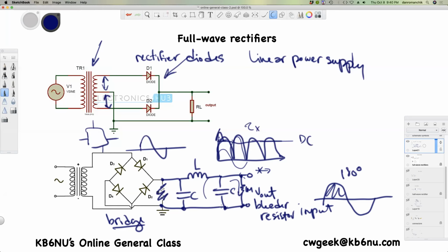So that bleeder resistor will discharge that current right away, and the voltage will drop to zero. I even go a step further. Anytime I do something like that, I'll wait a minute or two, then put my multimeter on it just to check and make sure that there's no voltage left across the output terminals. And if you're doing that, make sure you unplug it from the wall too, just to be safe. It's always best to be safe.